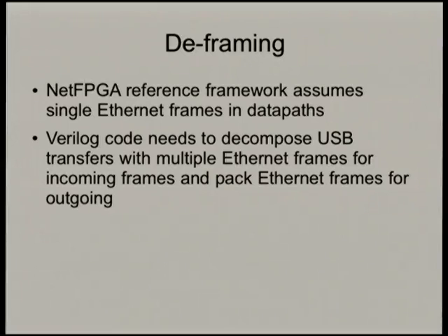So the Verilog code needs to read through the chains of headers and take each Ethernet frame out and present them to the NetFPGA switch reference design one by one. Similarly, when frames come through that need to go back, we need to repacketize those, and there's a bit of timing involved there to know just how many to repacketize. So there's a bit of work to be done there yet. It's not working yet, by the way, if you're wondering.